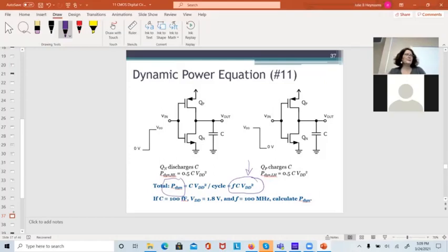So if I want to get the power down for free, there's three things I can do, the most fundamental things. I can lower the frequency, which means my cat videos load slower. I can decrease the capacitance by making the W times L, the overall dimensions of the devices, smaller. So I can make my process smaller, and then maybe bump the speed up a little bit higher and get the same power dissipation.